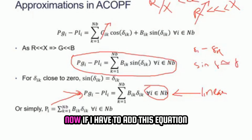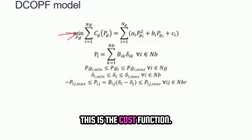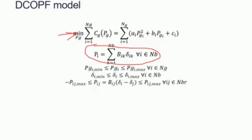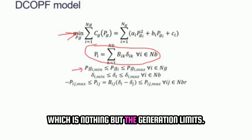With this, now if I have to add this equation in economic dispatch, which will eventually lead to the DC OPF, let us see how it looks. So the DC OPF model looks like this. This is the cost function. It is the same as in economic dispatch. Instead of the power balance equation where sum of PG equals PD, I am writing this, which is Pi is equal to Bik delta ik, for all the buses. This equation is again the same as in economic dispatch, which is nothing but the generation limits.